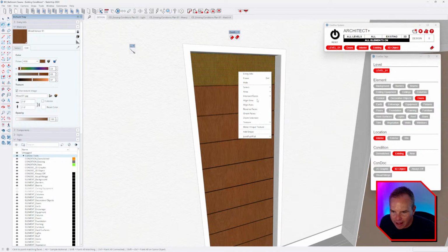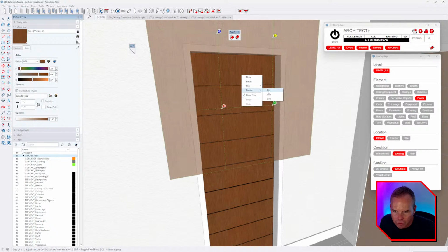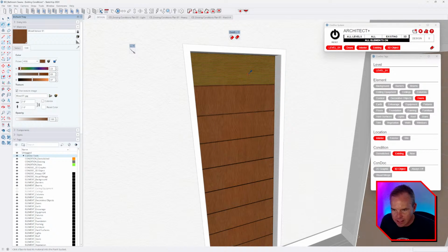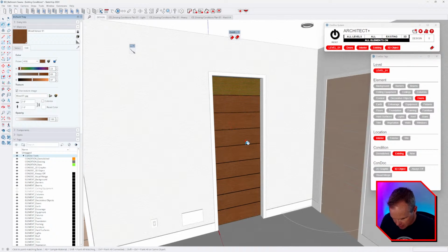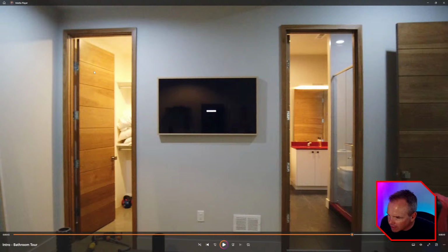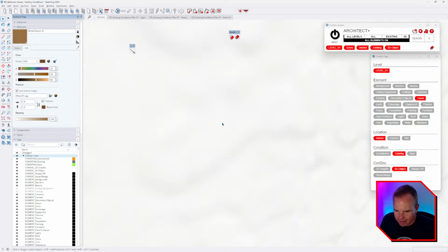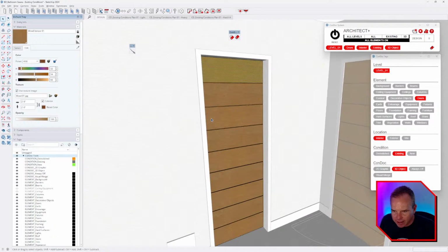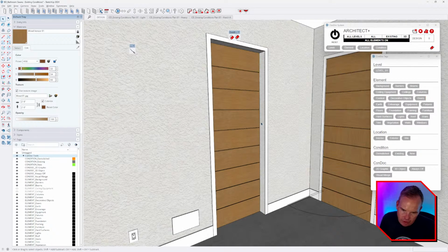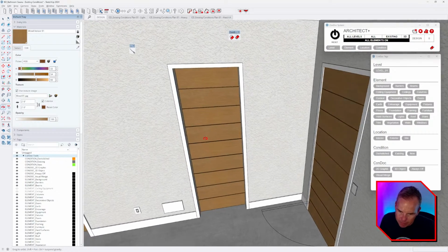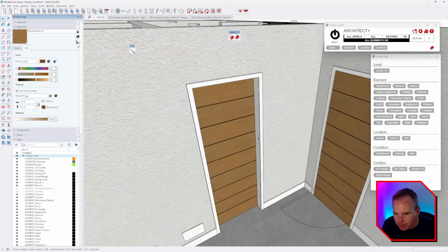And you have to do that and then go to texture position, rotate 90, enter, and then sample that rotated. And then we're going with more of a golden tone on that. So I can edit this, colorize it, and definitely, yeah, something like that. And again, if I were doing renderings, once it gets over into Lumion, I would be more apt to just swap it out with something they've got going on over there. Okay, so that looks decent.